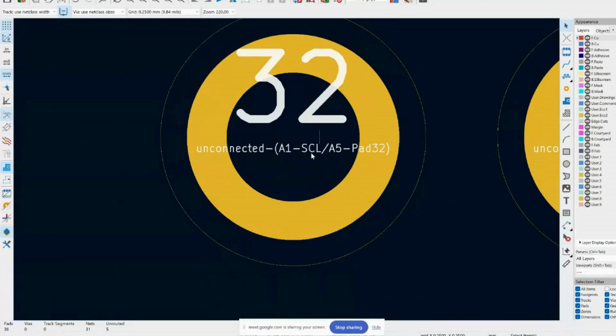If I were designing this board, I would spend an hour checking this part because if I got this wrong, the whole heart of the board is incorrect. I would fabricate the thing, it would come back, and I would have a pin wrong, and it wouldn't work. So that's the key thing to do here before we do anything else. You're going to pick all the parts you want, you're going to put them on the board, and check that they're right before you do anything else. Okay?